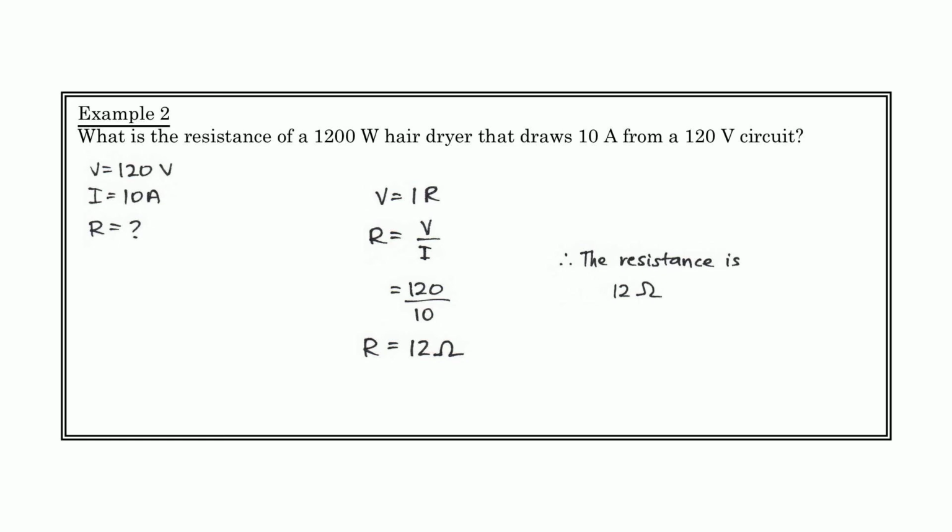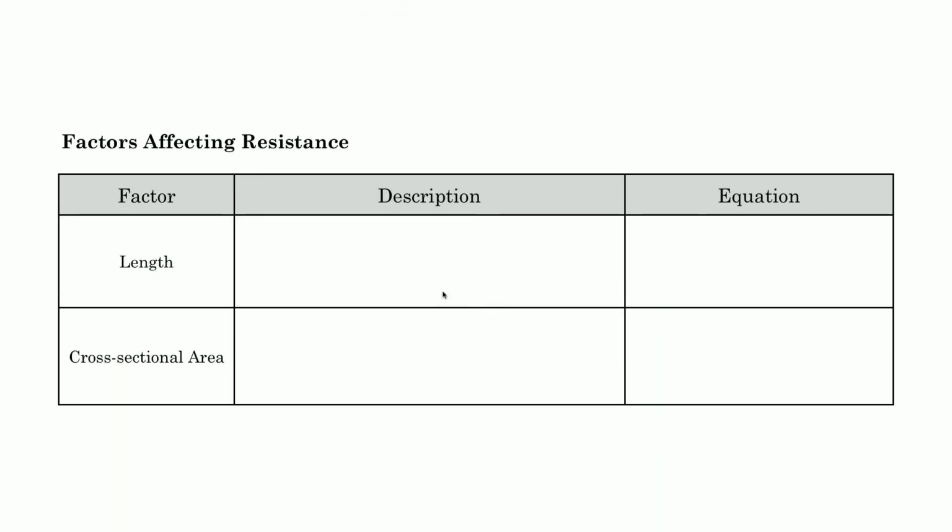There are a few things that affect the resistance of wires, okay? One of those factors is length. If you have a wire that's long, you will have much more resistance. This is one of the reasons why very often they tell you don't take extension cords and connect them end over end over end so that you have this huge, long wire, because you change the resistance. And because you change the resistance, then you can affect other parts of whatever it's connected to.